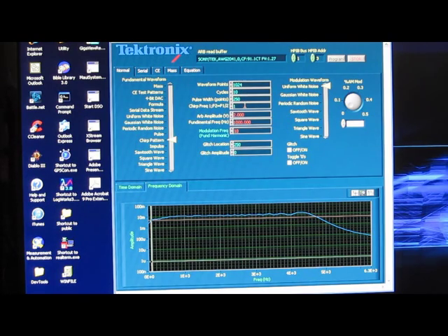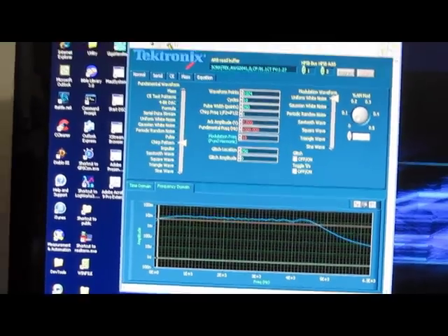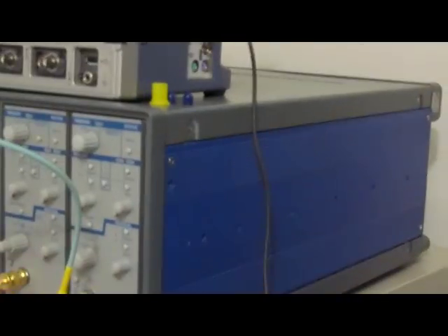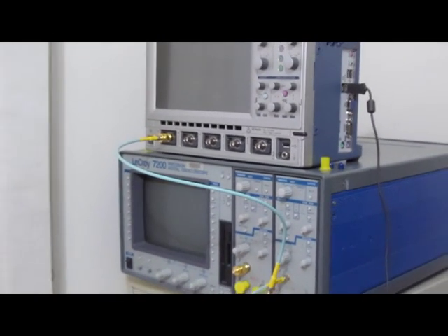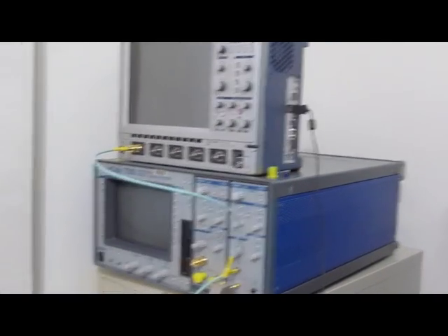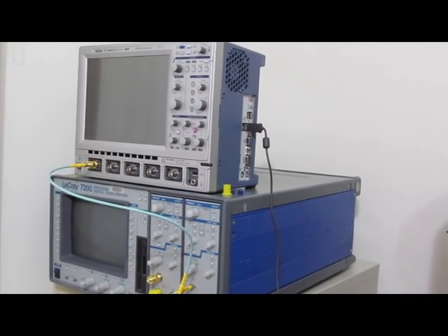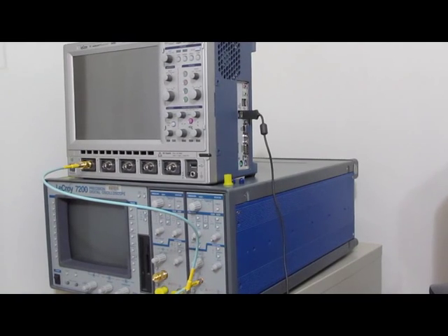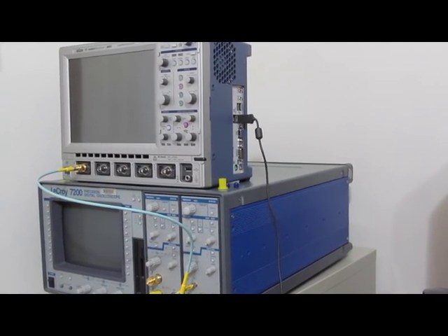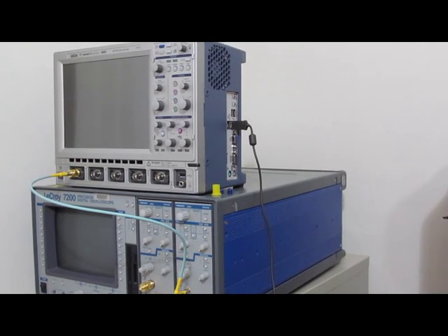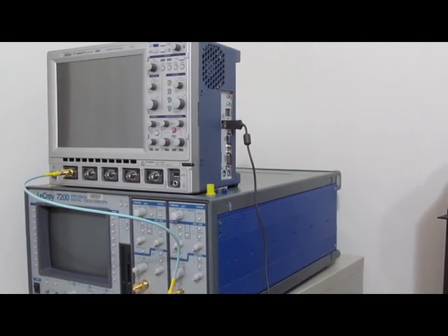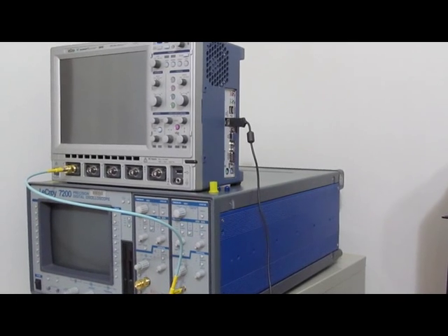As I'm going through and evaluating the oscilloscopes, I may actually modify this program if I can think of different test cases that may cause problems with the oscilloscopes. One of the things I'm thinking of is because the oscilloscope is sitting on the one side of the room here, where all my test equipment is up on the other side of the room, I may end up running the rest of the tests with a 7200A. It does have a newer high-speed plug-in, and it has larger memory in the 7242B than what this particular plug-in has. The main difference between the 7200 and the